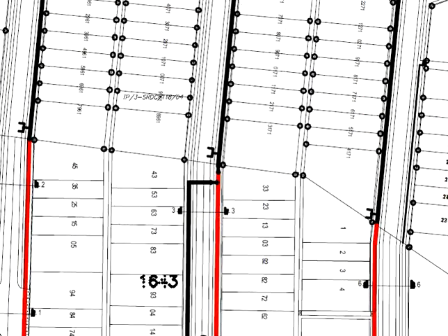However, there may be development in the adjacent lot. Now, theoretically, when it comes to the development of the adjacent areas, no development is allowed outside the lot boundary. Now, if you do not have the water reticulation systems reaching the boundary of the lot, there will be trouble tapping the water reticulation systems into the existing mains.